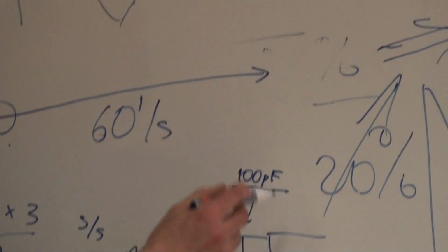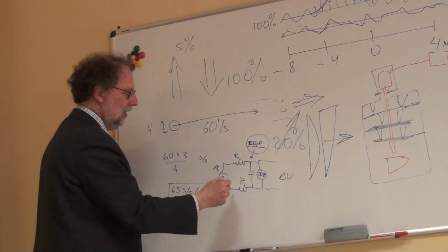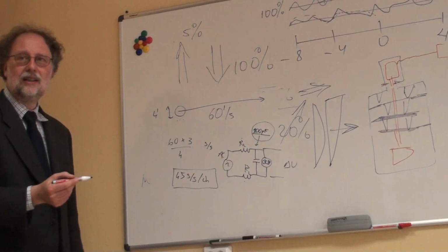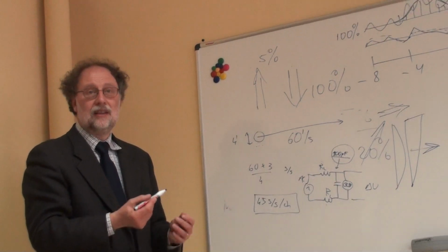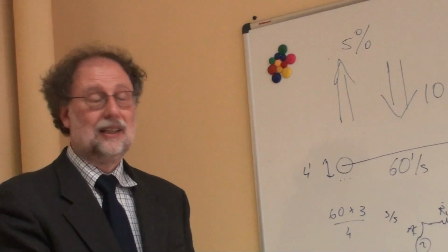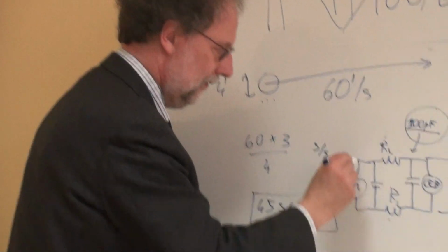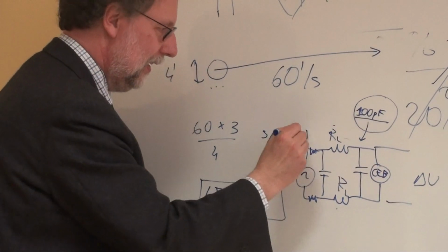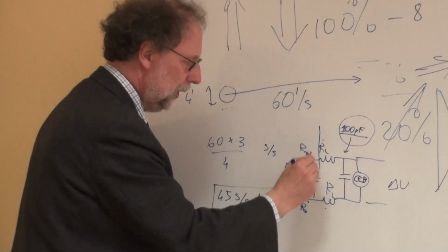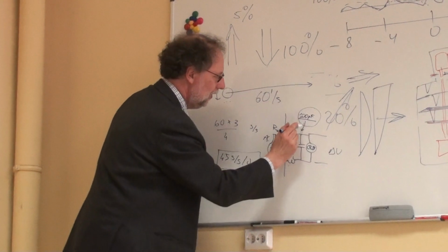So you cannot use a high frequency bias depending on how large the load resistors are. Because if you are in the 10 megaohms or 100 megaohms range, these are the wires' resistance, and this is on chip, as I understand, right? Yes. So this is very small, this is large.